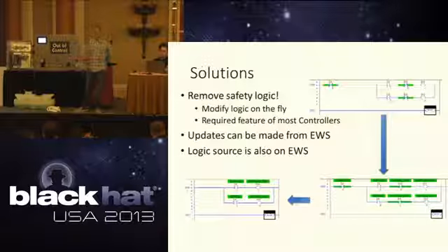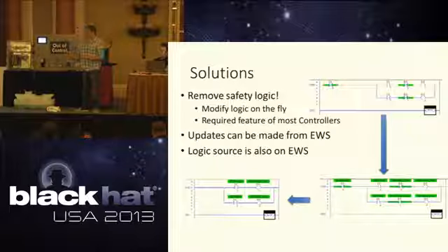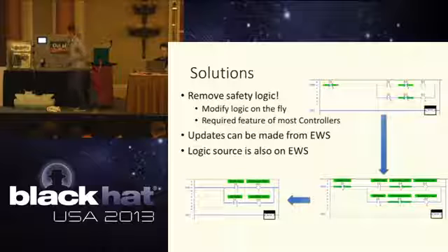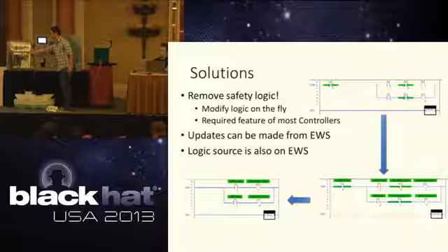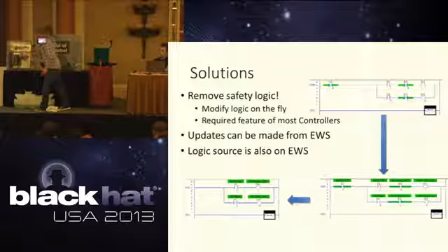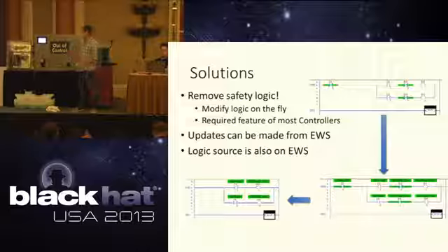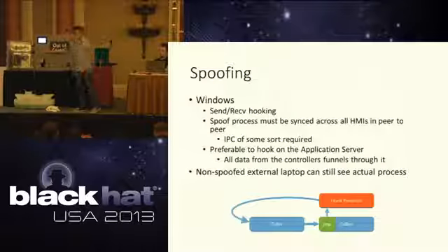We don't care anymore. You can overload it, and the safety logic will not prevent anything from happening, because we just removed that safety logic and re-downloaded. They call it download to PLCs. I don't know why, but they do. You download that new logic to the PLC while online, and your safety logic is gone. Your process still runs normally, but there are critical safety features that are no longer present in the logic.